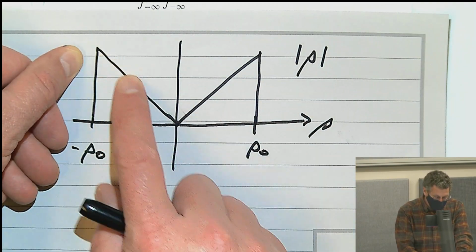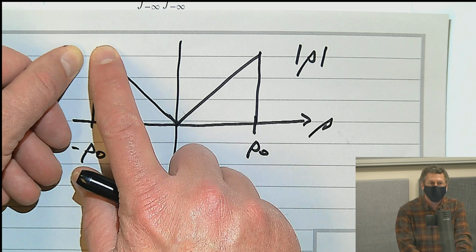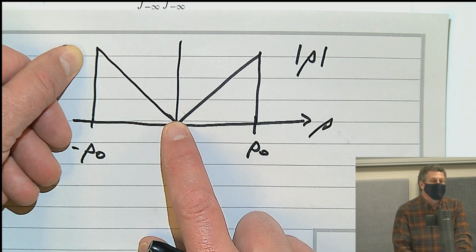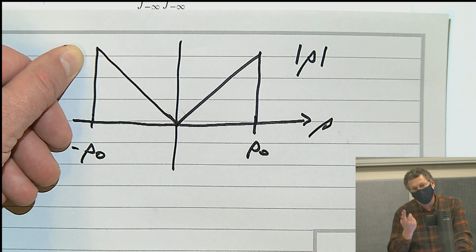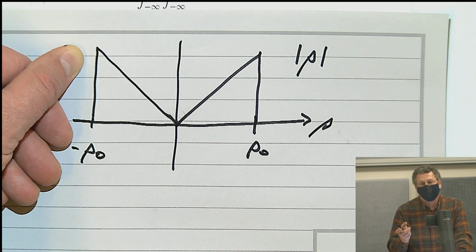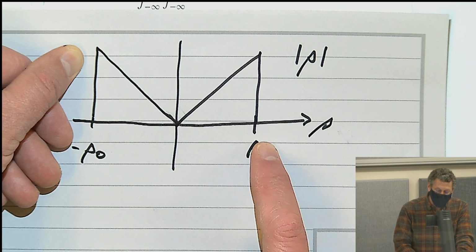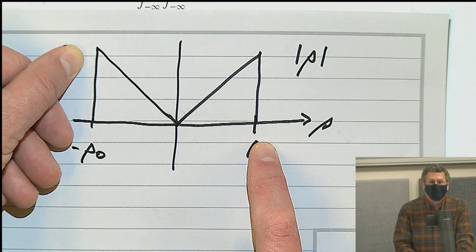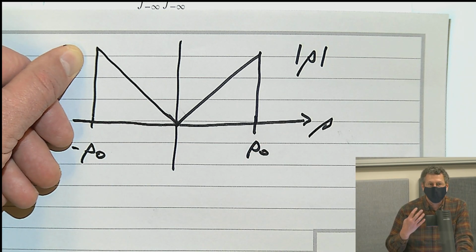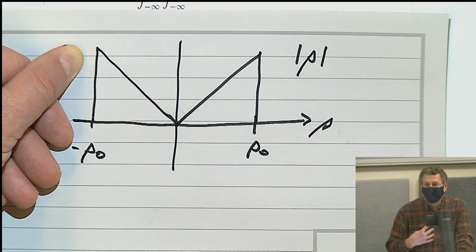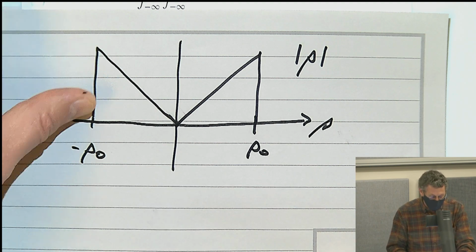And this thing looks like a triangle, which also has an analytical form. The triangle is formed by the convolution of two recs, so its inverse Fourier transform is a sinc squared. So the result is going to look like a sinc minus a sinc squared, and I can get an analytical expression for that.